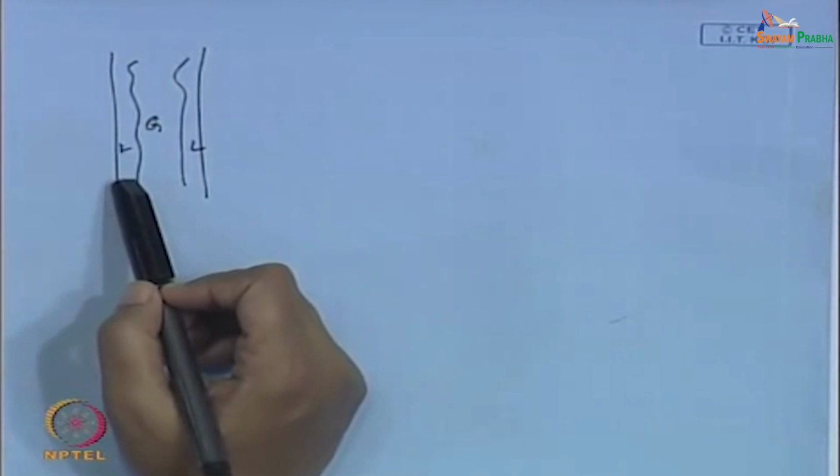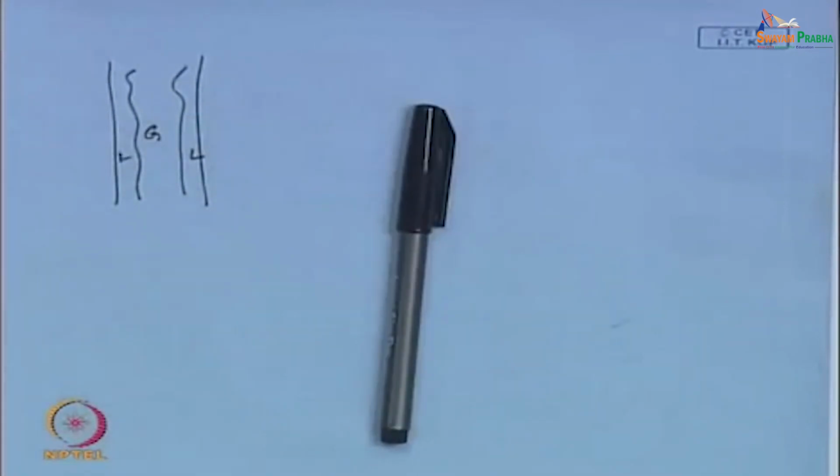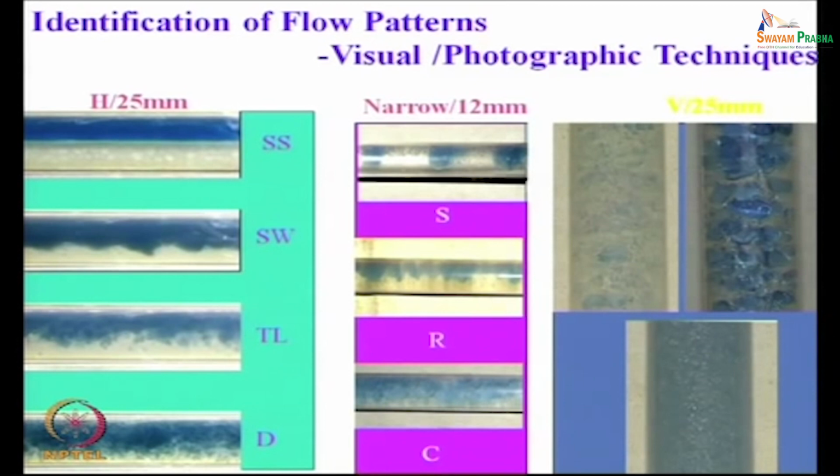On the other hand, for liquid liquid cases, either of the liquids can wet the pipe wall. Surface wetting properties are not very important when we are dealing with quite large pipes, where the surface energy is much less than the inertial energy, gravitational energy, etc. So, depending on the relative proportion of the two liquids, either of the phases can wet the pipe wall and either of the phases can remain dispersed in the second phase.